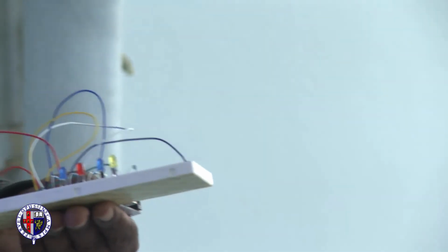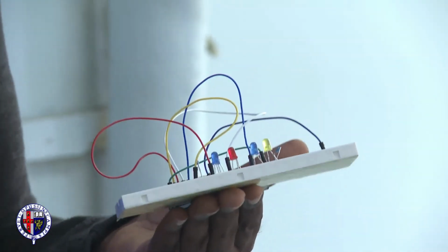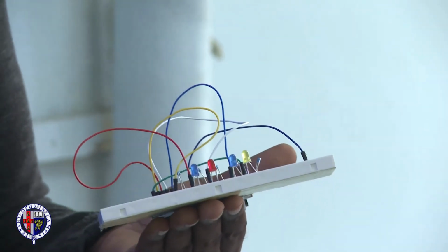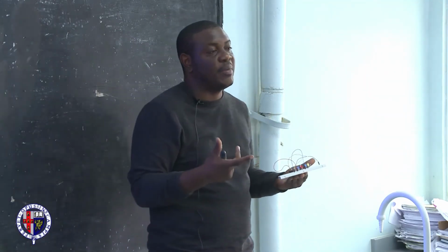And also in the kit come motors. So all of the motor concepts: you put a small voltage, you observe how fast it's spinning, put a higher voltage, notice it's spinning faster. So you can have all of those correlations between voltage and the speed of rotation, or between voltage and the force you get from Fleming's left-hand rule, to go deeper into the whole academic thing. So that is the rationale.